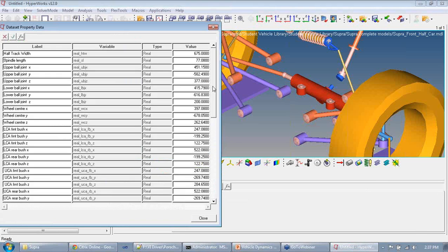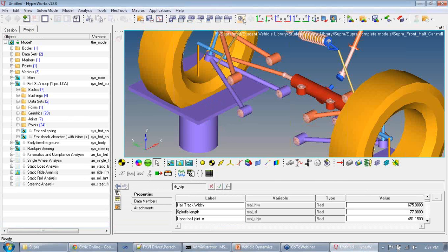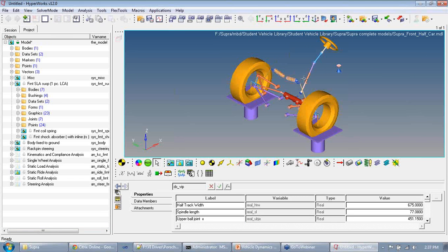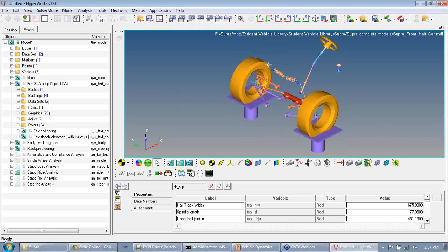So also the different points of the suspension can be moved around. This component here is called the rocker. It's essentially a triangle, and you can change its dimensions significantly by moving the coordinates around. So it is highly recommended that while you are working with CAD or directly working with MBD models, these are the parameters that you change one by one to evaluate your suspension design.